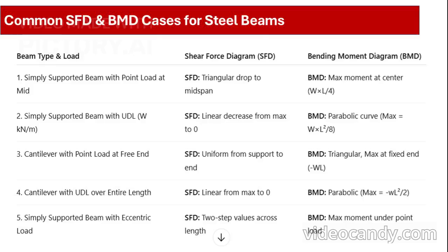Understanding shear force diagrams, SFD, and bending moment diagrams, BMD, is critical in structural steel design and frequently tested in the G+4 exam. For a simply supported beam with a central point load, the SFD shows a sudden drop at the load point, and the BMD has a maximum value at mid-span, calculated as WL/4.